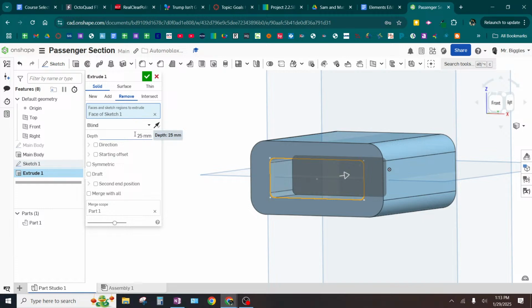So when you want to measure the depth of a hole, you put this in the hole, and then you bring the calipers back down until they rest on the lip of the hole. I got 11. Do it one more time. Extend this, set it where you want to measure the depth of the hole, and then just bring them back down until they rest on the lip. Okay, I got 11 again.